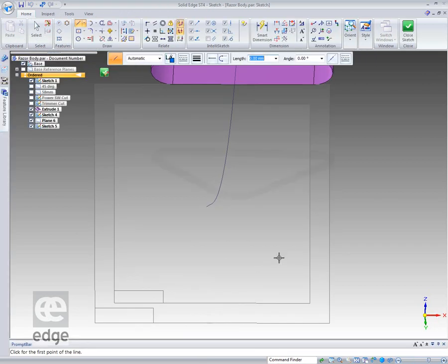And we want to sketch on that plane. When I'm sketching here, I'm just going to turn it off a little bit so you can see that end of the straight line, and I want to put an ellipse on here by the center point. Now notice that glyph that comes up, that's called the pierce point. That's where that curve pierces the plane, and it needs to be 18 by 15 by 0. And there we go. If you want to put the dimensions on it, by all means we can.